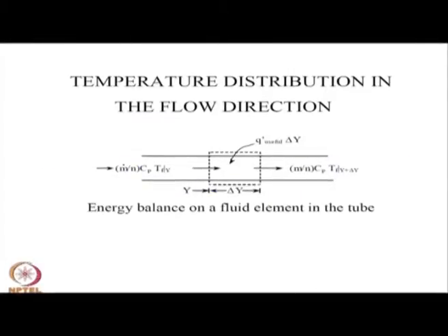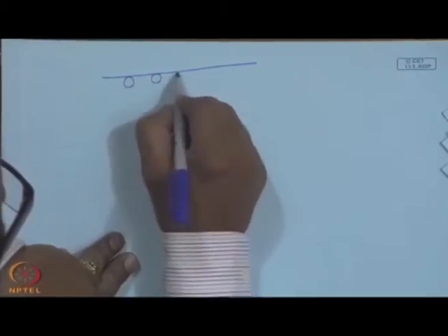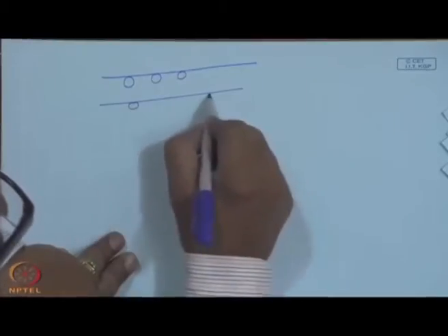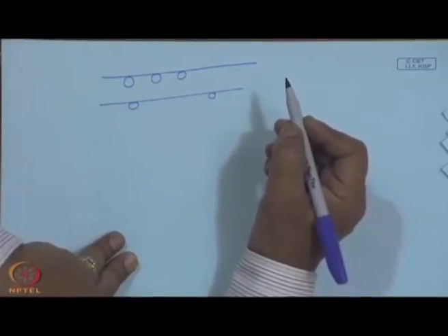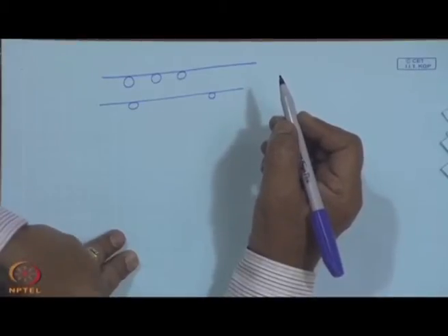So, now we got out of the two one dimensional equations, temperature distribution along the x direction has been obtained. From that, the fin efficiency comes into the picture, which will tell you whether these tubes are pretty close to each other or far off. So, that my fin efficiency will be lower because W minus D will be larger.